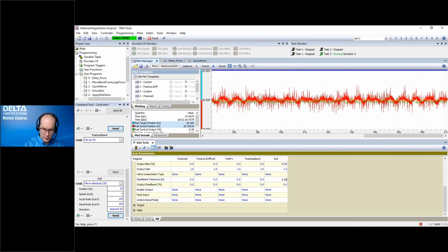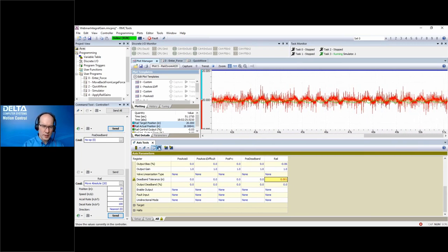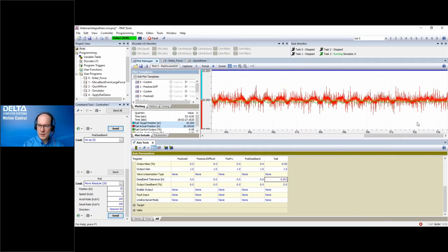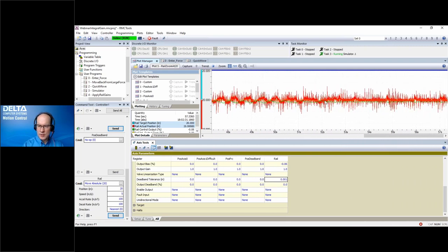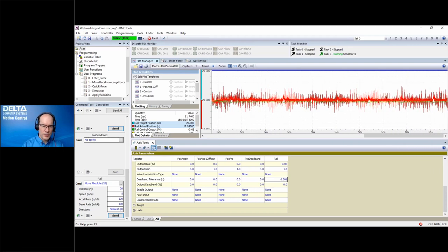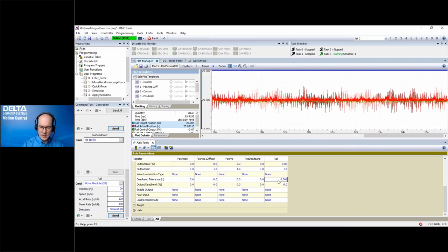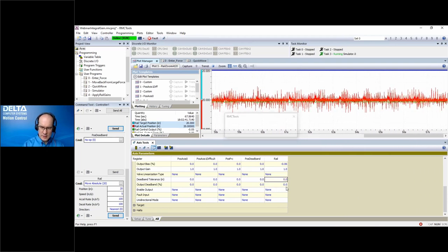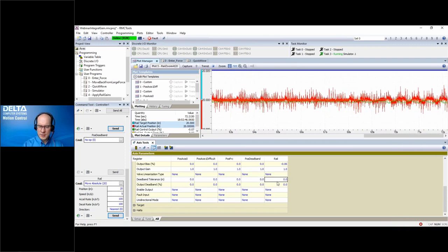So I'll set it to 1,000th of an inch. And watch when I download it. Look at the plots. We'll download it right now. And now the plot levels out. See that yellow line? It was going up and down, the integrator. Now it's constant. And the actual position is really, really close to 20,000. And if I set that back to 0, we see that it starts oscillating again.